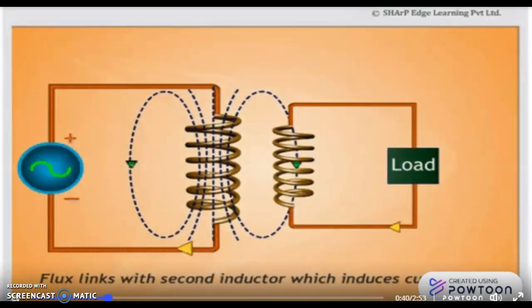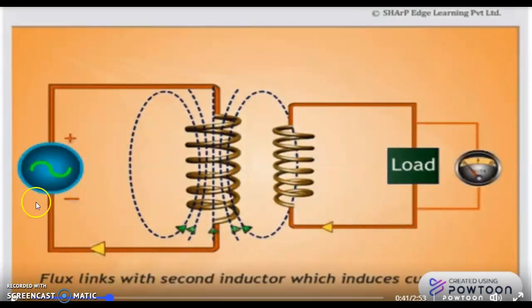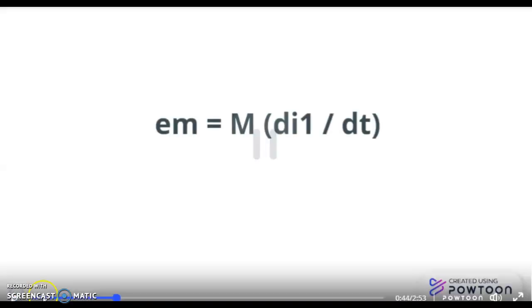Now, if you connect an inductor to AC mains, current will flow through it and it produces a magnetic field around and inside of the coil. If we then place a second coil close to the first coil and pass alternating current through the first coil, the magnetic flux it creates will induce a current in the second coil.